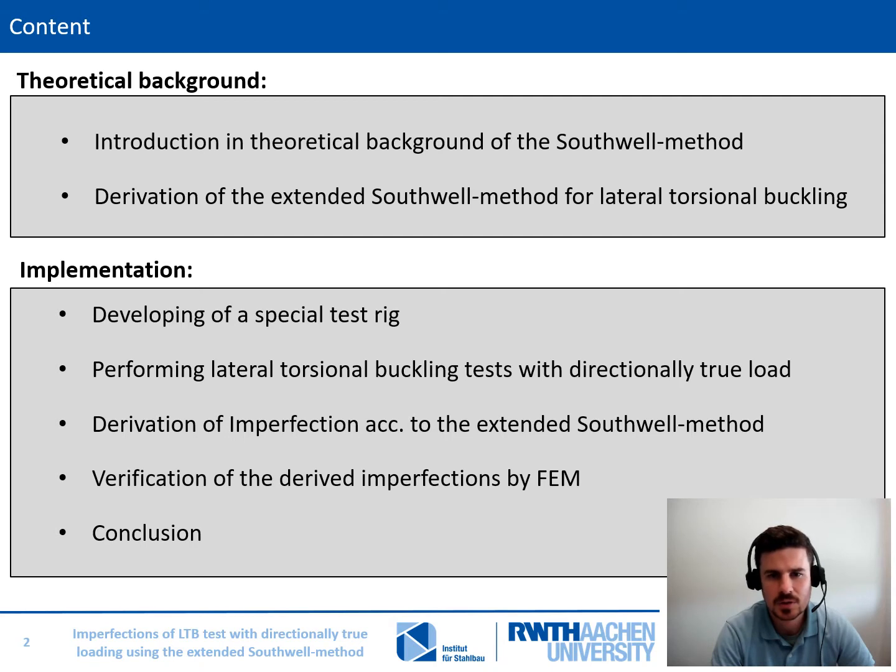First of all, I want to give a short introduction to the existing Southwell method for columns subjected to compression. Afterwards, I will go on showing the derivation of an extended version of the Southwell method for lateral torsional buckling to recalculate imperfection values. Keeping this in mind, I will go on with the implementation of the extended Southwell method.